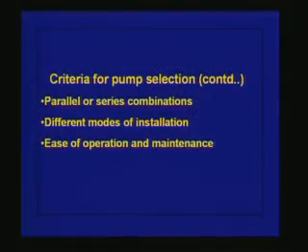Finally, the ease of operation and maintenance. The pumping installation should be such that we can maintain it easily, and we also have to consider what kind of operation is required, whether it is easy or difficult, because many times the operators are not well qualified to be able to implement a very complex operating schedule. So the operation should be such that it is easy to operate this pump and easy to maintain, and pump selection many times is based on that criteria also.